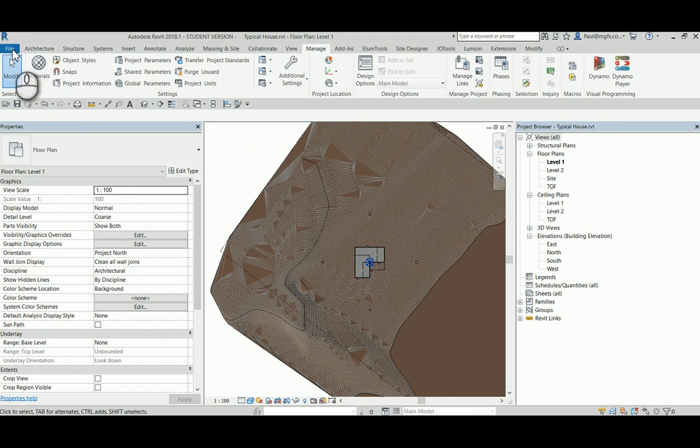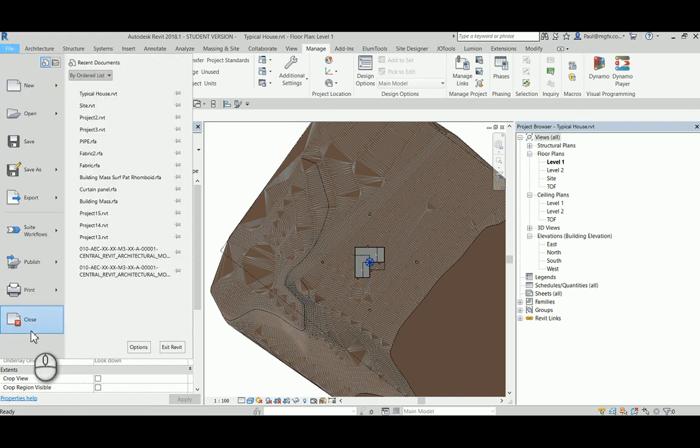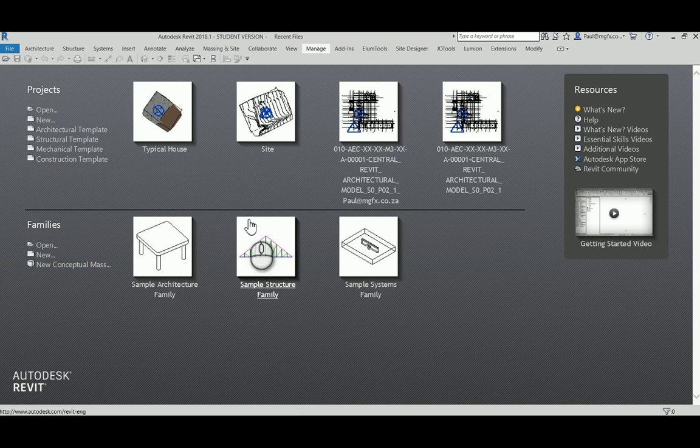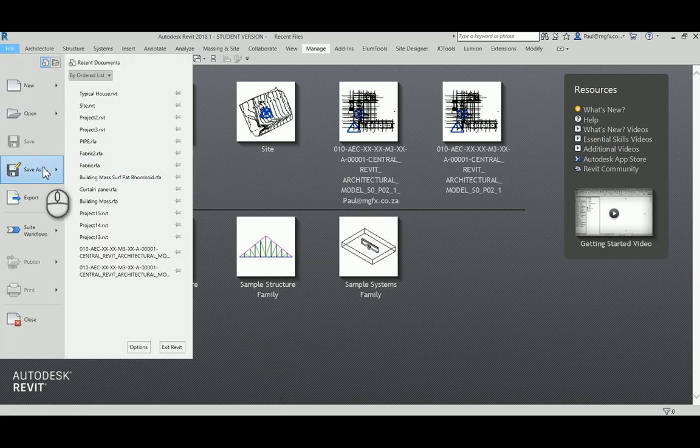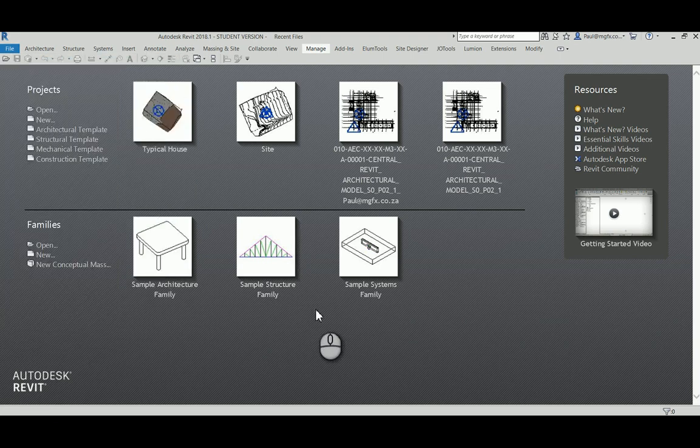It would obviously be a rough calculation because the really final grading will be done in a platform like Autodesk Civil 3D typically, and the final grading can then also be exported to DWG and linked into Revit, or otherwise a points file created for the topography to be created quickly.